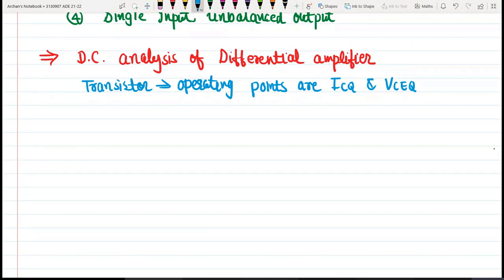We get the maximum point on the horizontal axis and the maximum point on the vertical axis, and then we draw a straight line covering both points, and then we have the actual characteristics of the device. Wherever this DC load line intersects the operating characteristics, that gives us the operating point of the device. Let us try to understand with the help of some graphics.